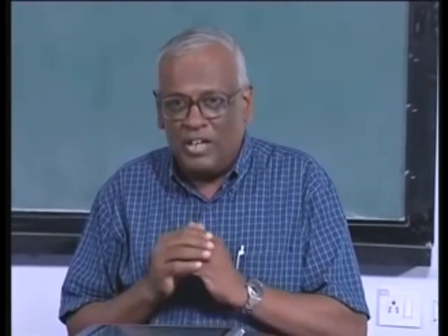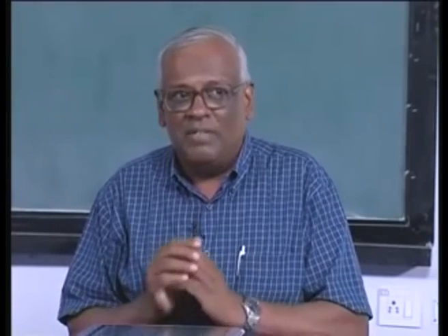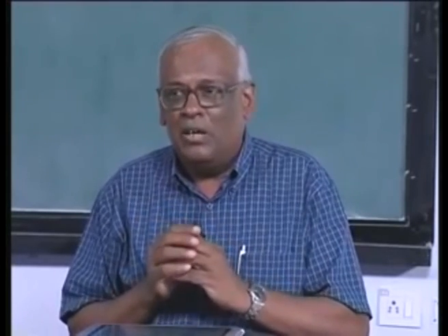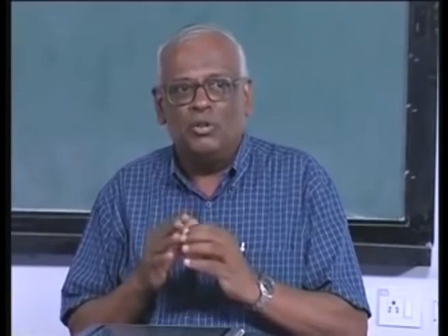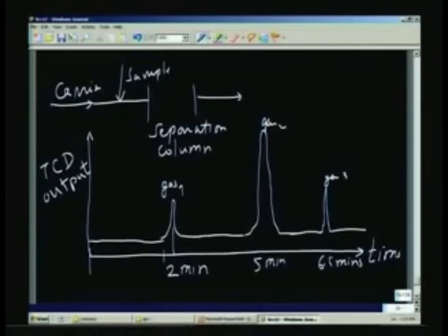For example, if I want to calibrate for CO2, I must have a carrier gas plus a certain known fraction of CO2, maybe 2 or 3 different concentrations, and use that to calibrate the instrument, so that quantitative measurement of the gas concentration is possible using the known gas concentrations in the gas mixture, which is supplied in a pure form. And of course, purity is very important, because if it is impure, the whole idea of calibration will become meaningless.